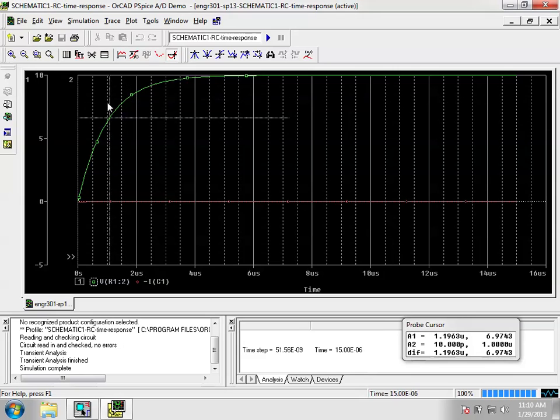Now, if I'm trying to estimate, let's say this 6.3 thing here. Notice the best I can get is 6.352. So what I want to hint at is that you're starting to get some sense of error show up here, and you want to try and assess that reading from PSpice. Try and see what your measurement resolution is. Okay.